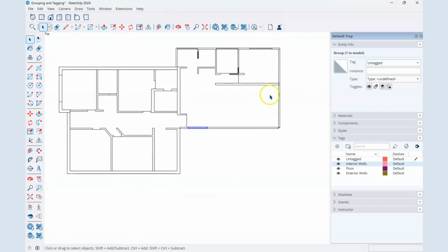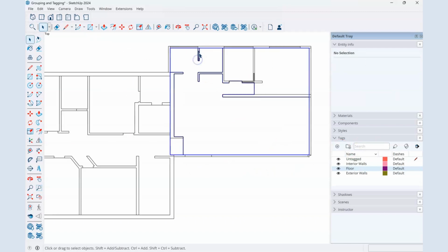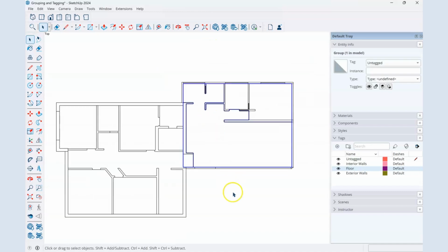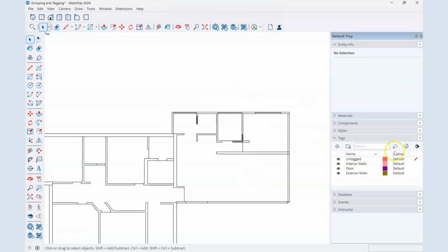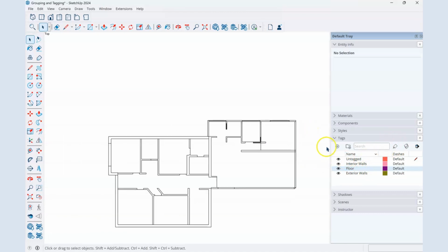Next I'm going to work my way through with my tags. I'm going to go with floor to start with, and I'm going to use this tag tool feature here. Actually, before I do, I just want to deselect everything. You could use this tagging option and have the tag selected that you want, but I actually like the method of using control.